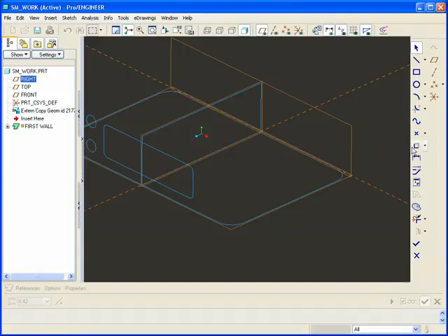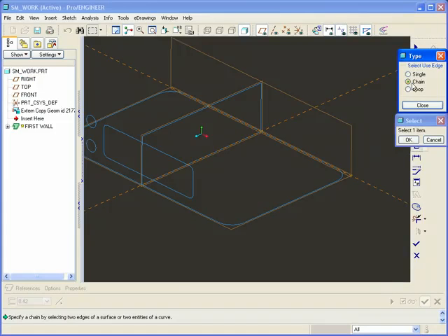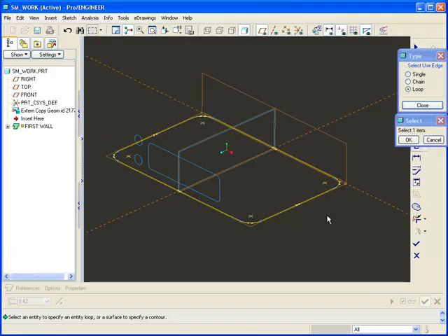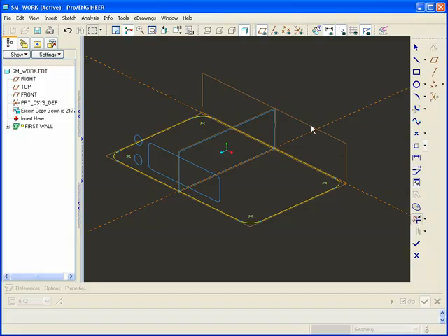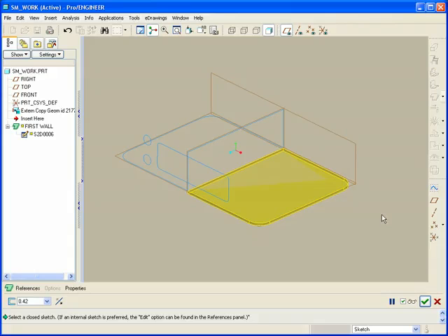So let's use Edge now. In this case, we'll use a loop picking up all the curves for the entire plan form. Now since this model happens to be symmetrical and we want to keep this tutorial somewhat short, we're only going to build half of it, and we'll utilize the mirror command as well. We're going to use the squiggle trim tool to pull off half of it, and then because it's a flat wall it needs to be a closed sketch, and so we'll drop that closed.